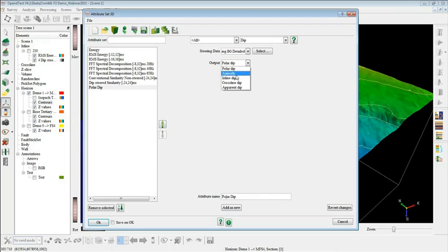There are optional attributes which are the components of dip, like in principal direction, inline or cross lines, or apparent dip. That's very interesting. This is a dip measured from a certain azimuth, so that gives a geologic sense. So you can call it apparent dip at 0 azimuth, and you can change these values like 45 and 90. So this azimuth is made from true geographic north.